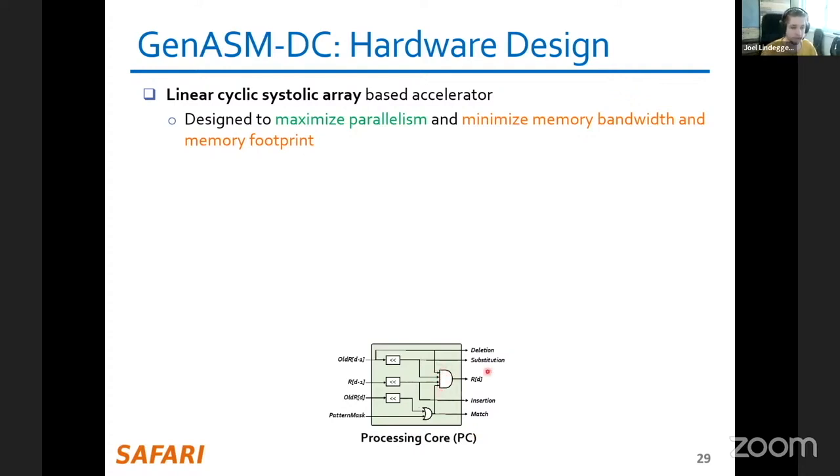This is just a single instance of this, and all of these are 64-bit wires. But it's really efficient in hardware. In fact, these bit shift operations, in hardware, they're not even operations. A single bit shift in hardware just means you move some wires over. So you could even ignore this part. And then it's just a 4-input AND gate and a 2-input OR gate. So at the lowest level of hardware, it's really efficient.